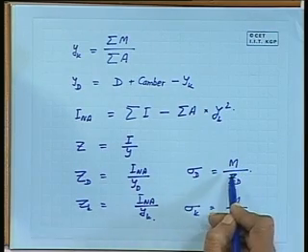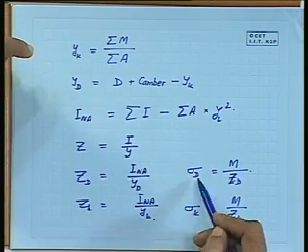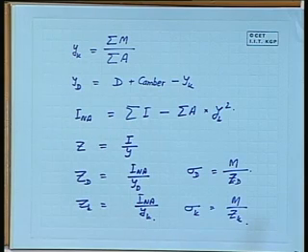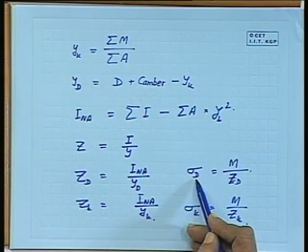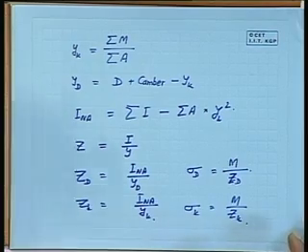Okay. And therefore, if I call this maximum here, then these are the maximum stresses, and if it is a hogging condition, deck will be in tension, sigma d will be tensile, sigma k will be compressive. If it is a sagging condition, sigma deck will be a compressive stress, sigma k will be a tensile stress. Fortunately for steel, the permissible limits in tension and compression are identical, but there are materials which do exhibit different properties under tension and compression.